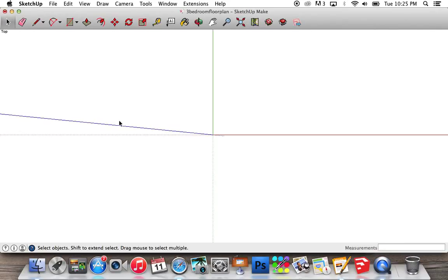So let's start drawing our floor plan. Let's say I have a new build. I'm still in the conceptual phase, but I do know that our home is going to be 46 feet 6 inches by 34 feet. So I'm going to go ahead and activate my rectangle tool up here, or press the letter R.